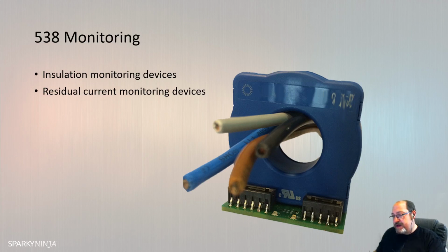You've got then a nice table in Annex A53 on page 188, which is a bit like the switching table. It gives us device functions and coordination. So if we were to say, can an RCBO be used to provide switching only? No. Can a contactor be used to provide overload protection? No. So that's just a fairly simple table to navigate.